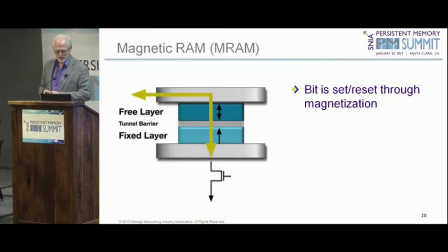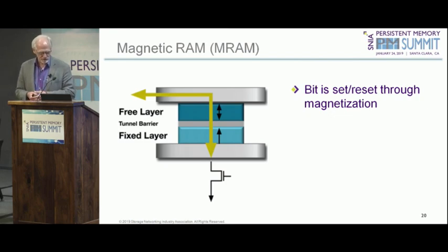So first of all, MRAM, we talked about it before. This is basically the spin torque, perpendicular spin tunnel structure. Here you've got a fixed layer, and you've got this free layer that can change its orientation. Depending upon the orientation of those two layers, the thin oxide layer in between them can tunnel electrons either really well or not so well, and therefore it'll have a higher or lower amount of current, or higher or lower resistance.